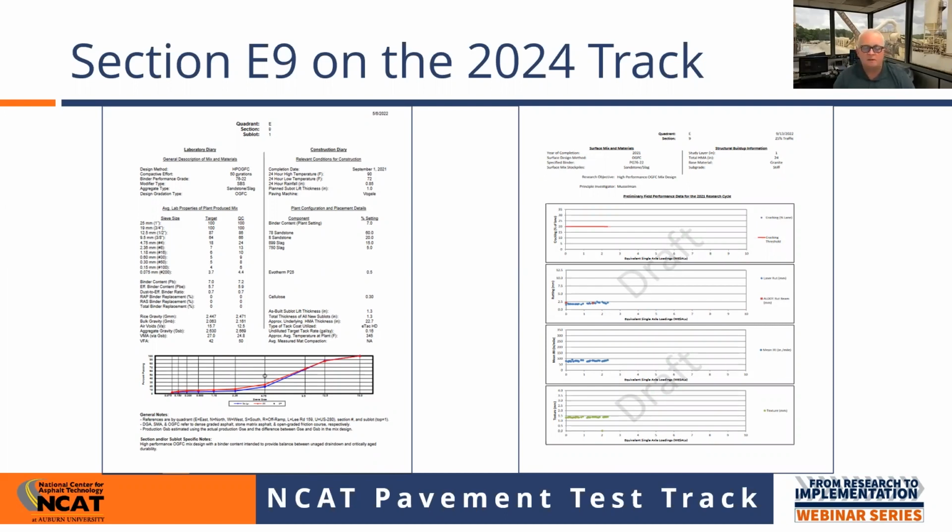I'm a big advocate of don't do 2 stockpile designs, don't do 2-bin designs. Have more material in the mix so that you have enough flexibility that you can tweak the gradation and stay on target. Jim, do you want to say anything about this before I move on?